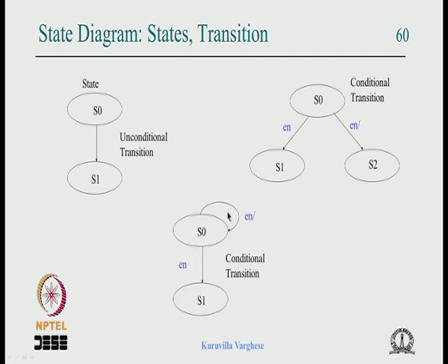Now there is another very useful structure here. The present state is S0, and there is an input called enable, and it could be called anything. As long as that input is 0 it remains in that state, however many clocks come, and when that input becomes 1 it transits to another state. So you can say we are waiting for something to happen, okay.